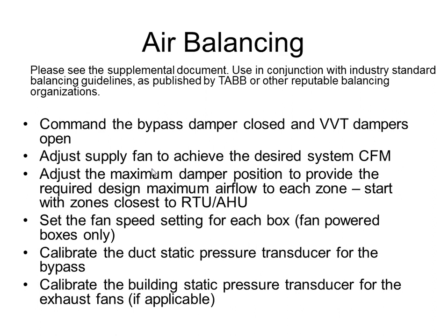But one thing I'd like to stress, the most important thing when it comes to air balancing is making sure you get an air balancer and someone who knows the control system on site at the same time so that they can coordinate how the control system works and how the air balancing is supposed to be set up. Personally, I've commissioned controls on many job sites where I haven't even seen an air balancer, and the air balancer never even shows up. And we can't control the system the best we can without an air balancer to help us.